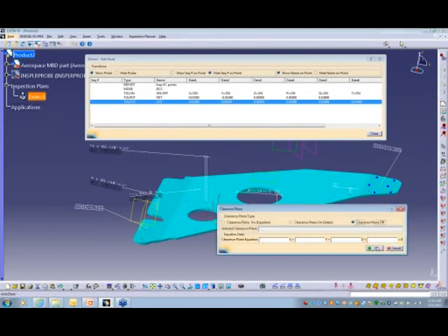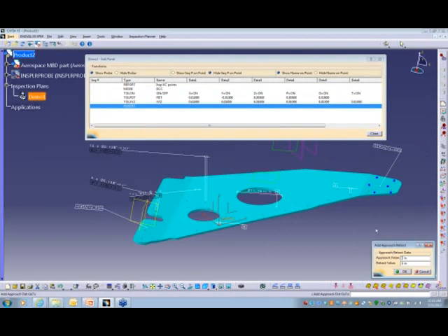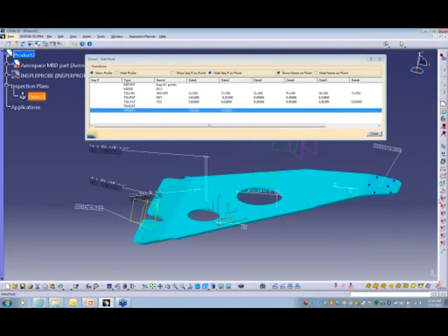We have a clearance plane. We'll have the clearance plane off. We can put approach and retract information in here. Here we'll put 050 because we're going to be measuring these holes later, but this is all CMM stuff that needs to be in the machine when it runs.